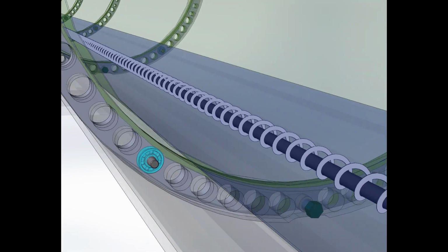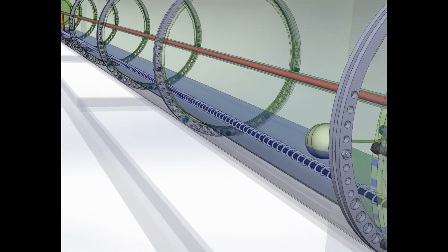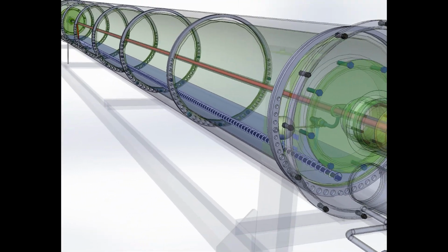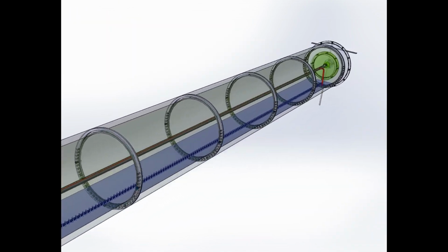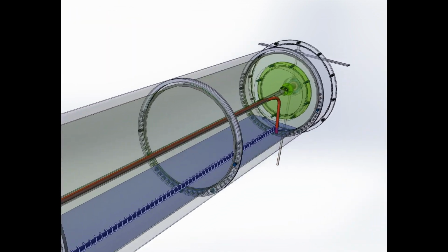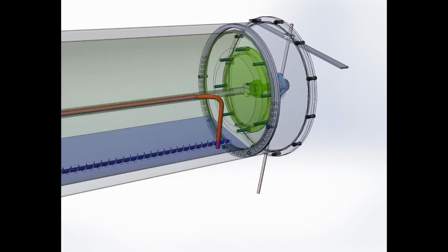The rotation of the belt and the impossibility of its movement in the longitudinal direction due to the limitation by the ends of the drum forces the belt to perform the function of a screw that moves precipitated particles from the bottom of the drum to the discharge side, where the suction section of the tube for periodically removing concentrate from the drum is located.